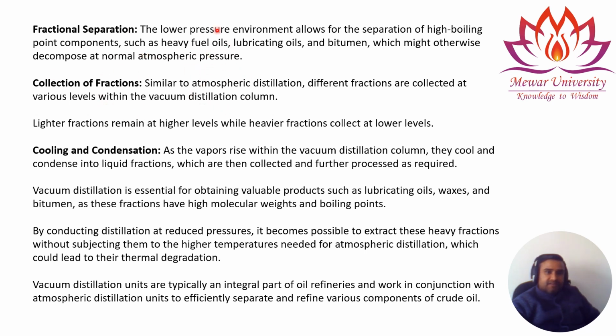After this distillation, it is important to collect the fractions. This collection of the fractions is similar to atmospheric distillation, and different fractions are collected at various levels within the vacuum distillation column, in different kinds of trays. Lighter fractions remain at a higher level while the heavier fractions collect at a lower level. So the lighter fraction will come at the top and the heavier fraction will appear at the bottom.